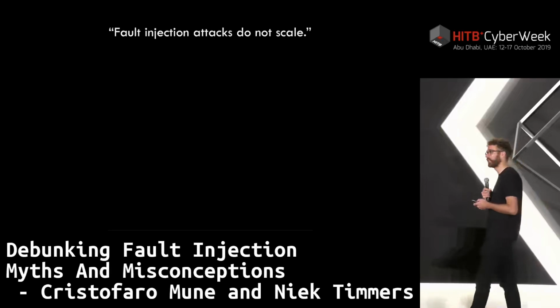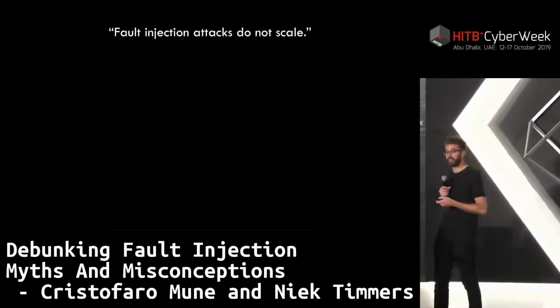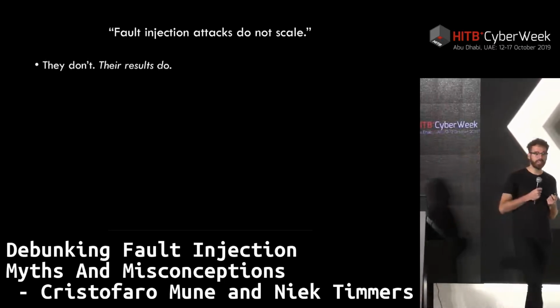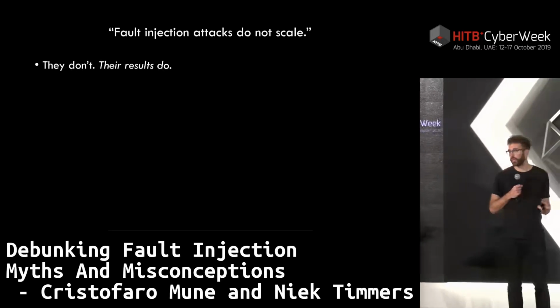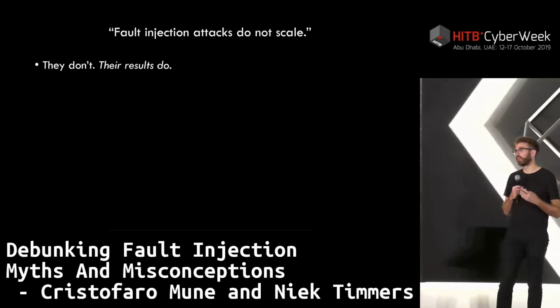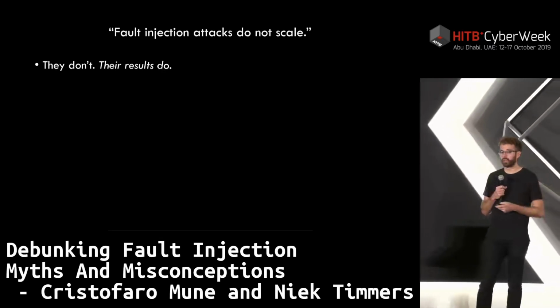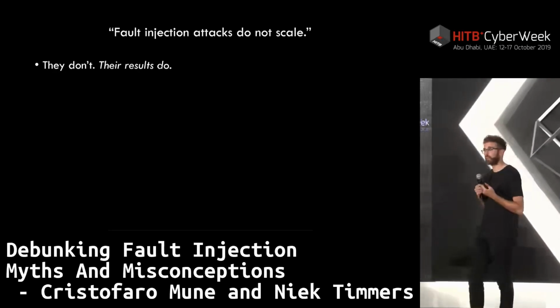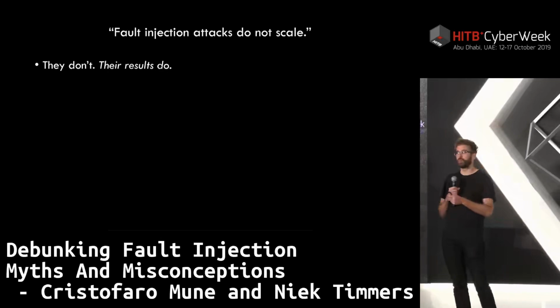Another interesting one, and this is again coming often from the manufacturers, is that fault injection attacks do not scale. Well, I mean, in a way, they don't. Not considering the software-driven ones, because they actually are a good exception to what fault injection attacks normally are about. But fault injection attacks itself, especially if you think of things like laser, EMFI, you really need to open things, you need to make modifications. It's very difficult to do it on the second target. Maybe the setup making takes just as much time. So the scalability of attacks is difficult,